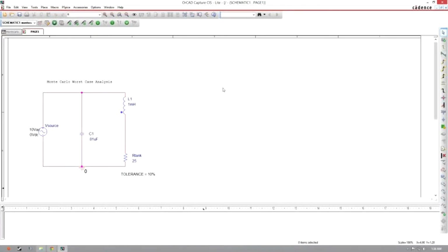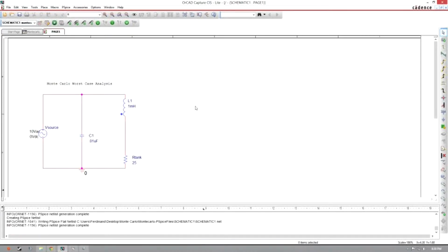Hello. The Monte Carlo analysis is a worst-case analysis for the circuit board in the case when components are accounted for their tolerances. Any good designer must know that any one part is not perfect. There will in fact be a tolerance to it, and parts will vary by a certain percentage off the factory line. Here below we have a tank circuit that we will be running tests with PSpice to let it tell us just what happens when a part does vary.